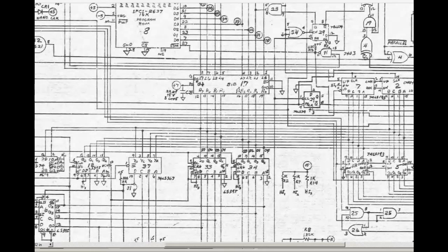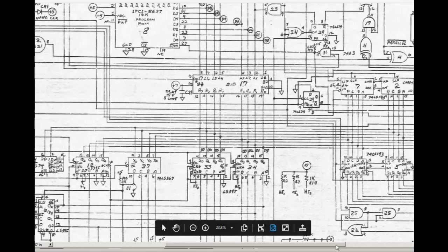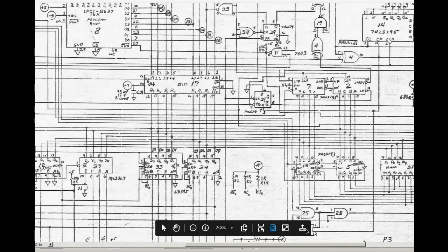So this device is a bidirectional binary buffer. It's also a level shifter, so it shifts levels between TTL, which is what we have on the main data bus in this printer, and the MOS level signals that go into the nano processor itself. But one of the things that makes this project a bit more complex is this buffer also inverts the data. So any data coming out, any data going in is inverted. And we need to take that into account when we are developing the simulator. And we can't just make the assumption that data going out is also inverted when it comes in.